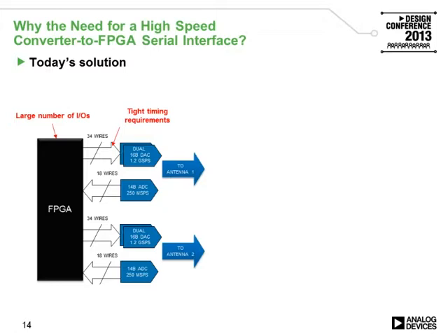Transmission lines need to have controlled impedance and match source and sink. Lengths of transmission lines used for differential traces need to be approximately the same. If not matched, the link can become unreliable. In such MIMO systems, the skew between 2 or more converter devices, called inter-device skew, is also relevant.